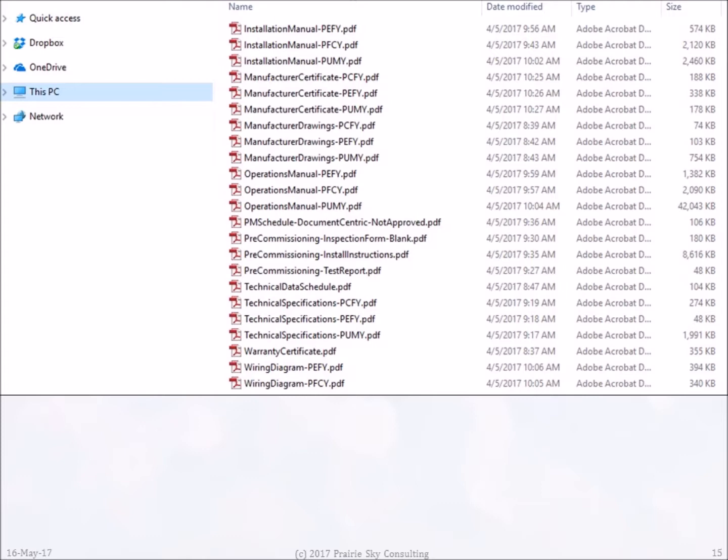Regardless of how you organize your submittal files, if you set it up beforehand, you can get pretty quick, as you'll see when we proceed. As you might guess, using COBie Forms for the submittals themselves is preferred to coming back after the fact. One final lesson learned. Make a backup of the original COBie form you'll be using in case you want to return to that original file.